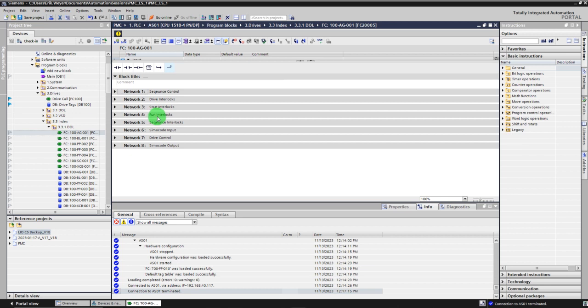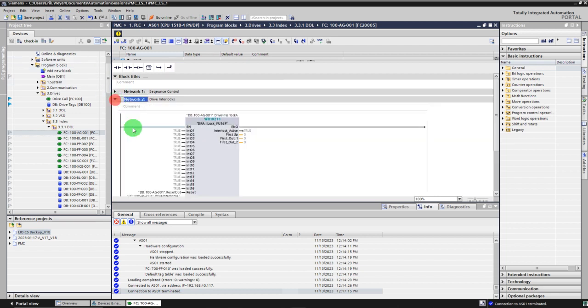So I've got my run interlock. My run interlock is going to be blocked for the duration of the run startup timer. That timer is defined on the drive faceplate, and we'll have a look at that later. And with my sequence interlock, this is when my drive is starting in sequence and I want a specific interlock to prohibit it from starting or stopping during that process. I can link a sequence interlock in here. But we're going to do a drive interlock just for now.